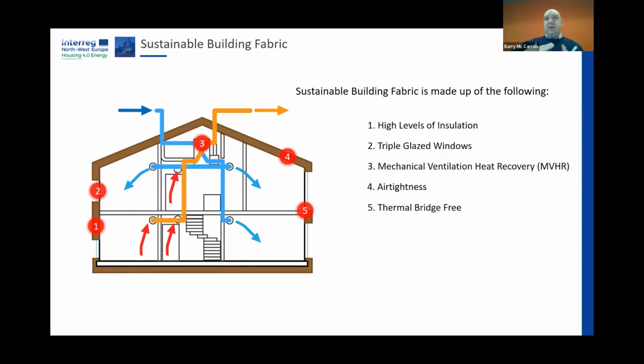That's basically the floors, the walls, and the roof junctions where each of them meet, and also where the windows obviously penetrate the walls. It's at these situations where you want to make sure that you've got a good enhanced detail, and that it's been assessed to make sure that there's no fear of condensation or mold. Thankfully, that shouldn't really be happening now anyway.